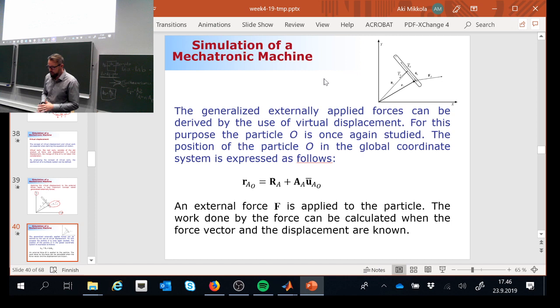Well, that's going to be very simple, because I'm simply going to use the kinematics that I'm very much familiar with. I'm going to first express the translation of the body reference coordinate system, then take into account the body orientation, and finally, with the help of vector g bar, I end up at the position where the force is applied.